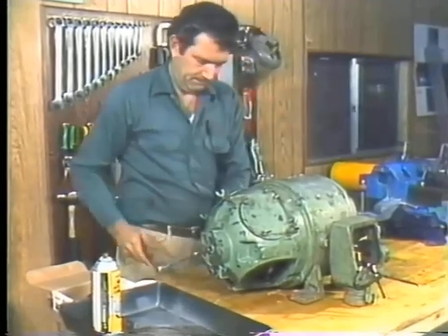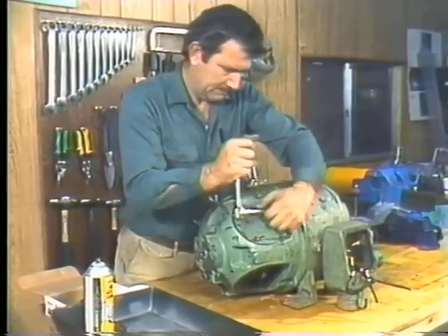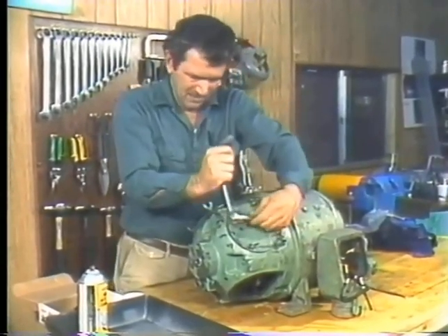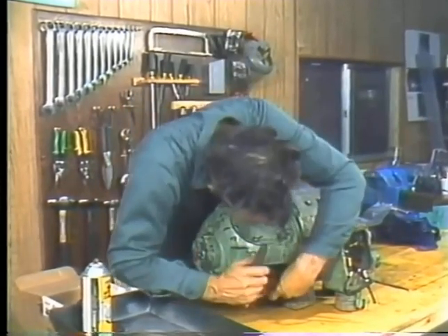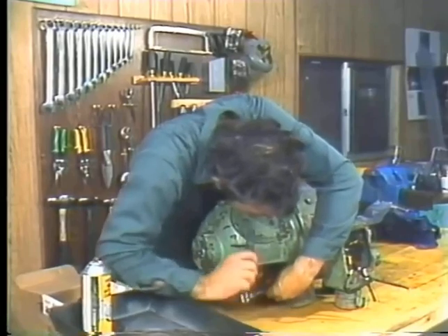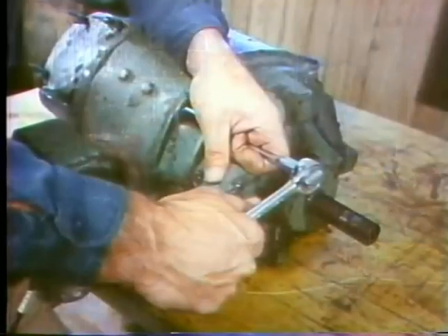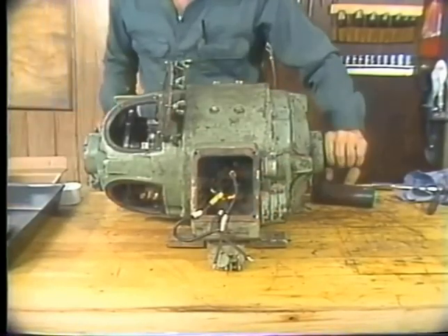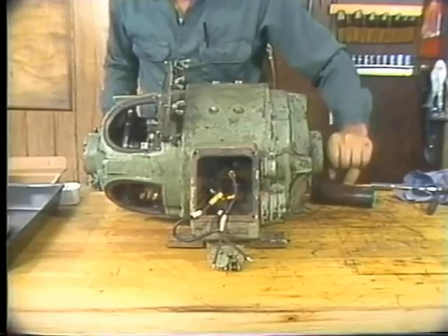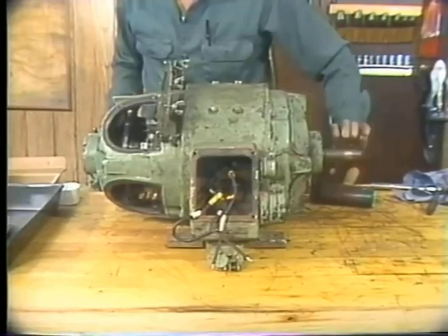As you work, keep an eye on the crack between the end bell and the frame. Try to keep an even space all around. Adjust your tightening of the bolts to compensate if it seems to be uneven. All right, now do the other end bell the same way. Turn the shaft by hand. It should and must move freely. If this shaft doesn't spin freely, you must recheck your work.